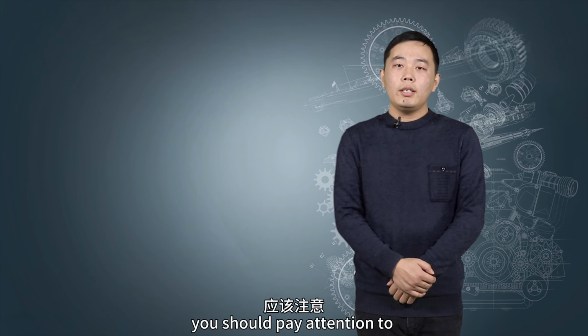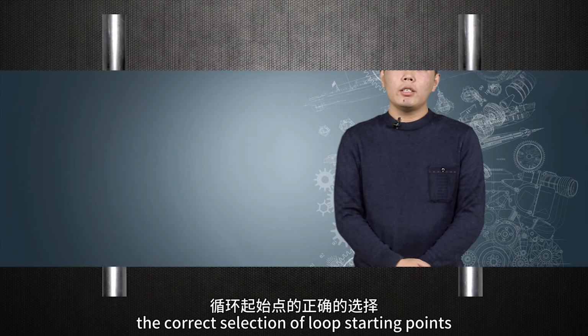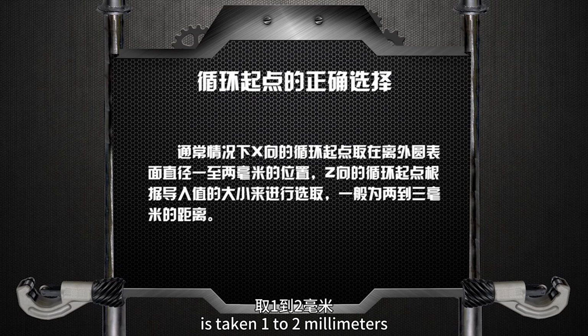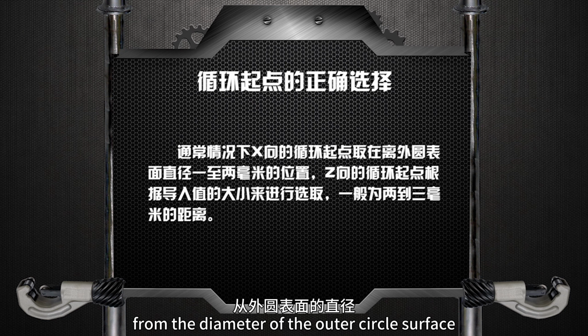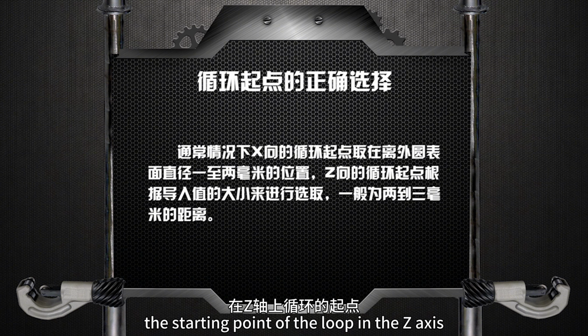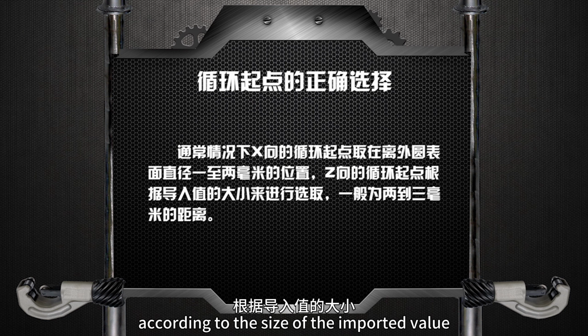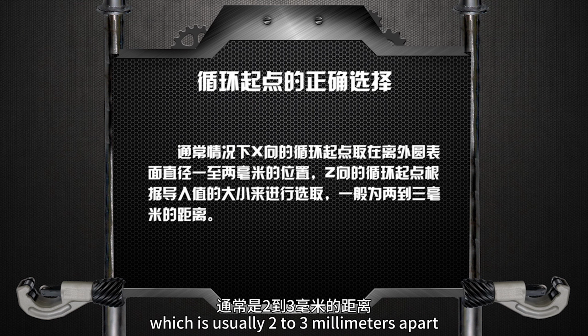In G92 cycle programming, you should pay attention to the correct selection of the cycle starting point. In general, the start of the x-axis cycle is taken 1 to 2 millimeters from the diameter of the outer circle surface. The starting point of the cycle in the z-axis is selected according to the size of the lead-in value, which is usually 2 to 3 millimeters apart.